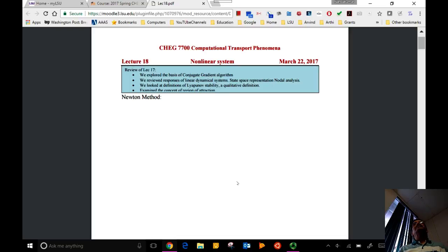Also, you said they are square cylinders. Yeah. And then you talked about the distance between these two having to be 2 times the diameter. So I didn't understand what you mean by the diameter of a square. There is this concept of an equivalent diameter for non-circular shapes. So you can use that. You know what an equivalent diameter is, right? 4 times the cross-sectional area over the wetted perimeter. That's a definition for non-circular objects. You can use that, or you can use the side. In fact, for a square, it turns out to be the side if you use that definition, the width of the side.